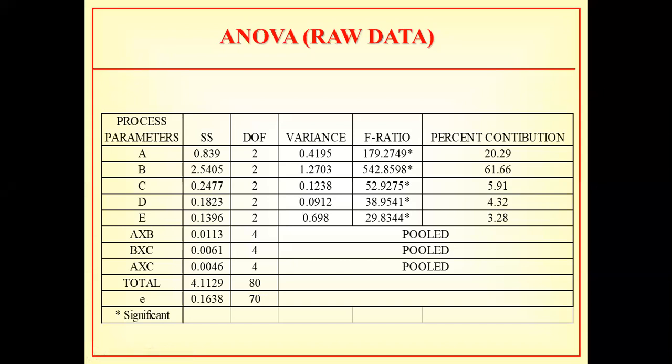If it is at 675 degrees centigrade, I need to control it as far as possible at 675, because any small variation, because contribution is more, my output will be affected. Say for example, the last one, 3.28, that is the time of vibration. Time of vibration is 30 seconds, say, even if it goes to 28 or 35, because contribution is small, it will not affect much.